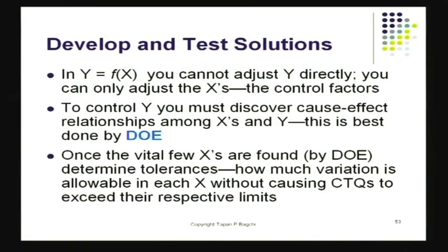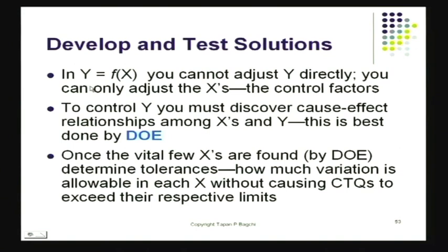So if you now see the progress of the Six Sigma project, you would probably find that what they are trying to do is establish y equals f(x), this relationship. Y is the response, which in this case could be the gluing strength, or the amount of force required to push a logo off the back of the car. The x's are those different control factors that I showed you. To combine all of them and look at the effect, this trial had to be done in the design of experiments framework.